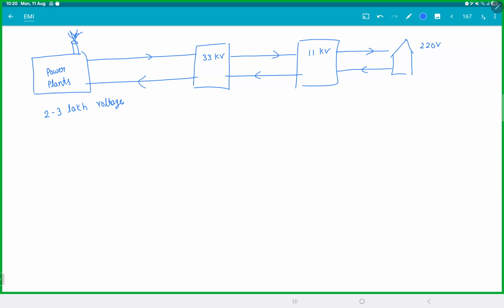Now the problem, imagine you have a power plant 200 kilometers away. You are literally using 400 kilometers of wire. No matter how good copper you use, it will have some resistance. Now, when you take it over 500 kilometers, that adds up to a large resistance. And if you're sending even half ampere of current, you get a lot of heat produced. Now, this is the scenario that will happen. I'll send you 100, you will get 50. You want to pay for 50, but I want the bill for 100. The remaining 50 is gone. Transmission losses will be huge. And this is where DC literally failed.